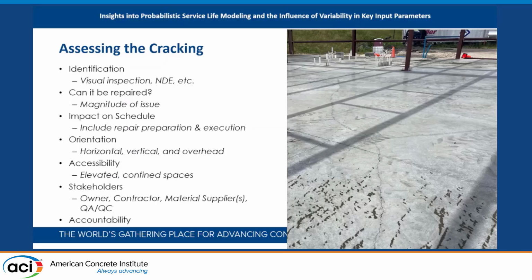Sometimes it's definitely under their control and they just screwed up, like in this slab on grade where the joints were sawn a little bit too late, and you have a beautiful crack that goes perpendicular to almost every panel. And now the owner is rightfully concerned that the structure they spent money on is not going to be performing the way they want. And sometimes that is correct, and there's a need for addressing the situation in perhaps a different way.